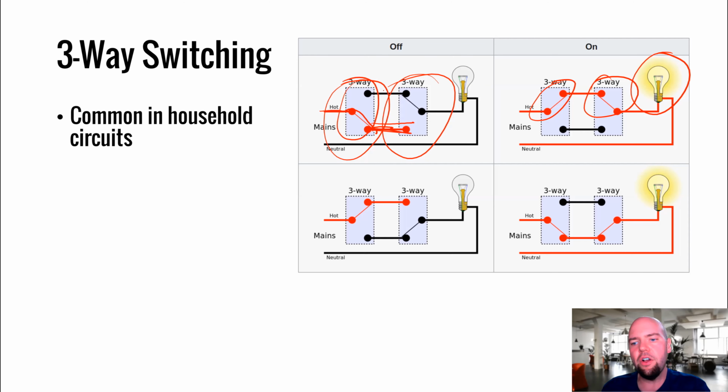So if any of you at your home have a switch where, to turn on the light, the switch has to be in the down position, that means one of two things. It means either it's a normal switch and the person just wired it upside down, so the switch is physically upside down, or it's a three-way switch, and somewhere in your house there's another switch that has the other wire energized. And if it drives you nuts having to push the switch down to turn on the light, go find that other switch, put it in the other position, and then you'll be back to up is on and down is off. So that's three-way switching. There's not much to it.